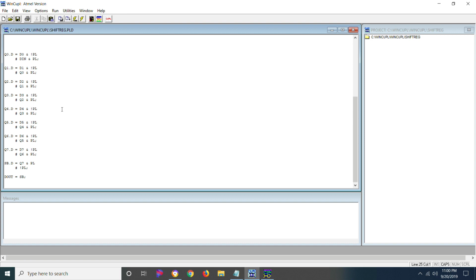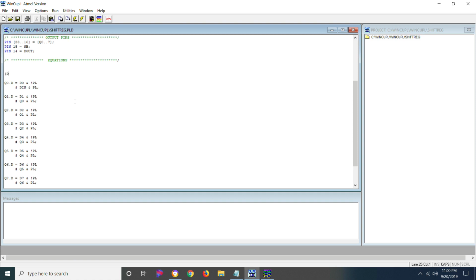And an easy way of doing that would be to do this, I believe. Well, I'm starting off wrong already. So Q0 through Q7 dot AR equals binary 0. And the same thing here. So Q0 through Q7 dot SP, synchronous preset, equals binary 0.